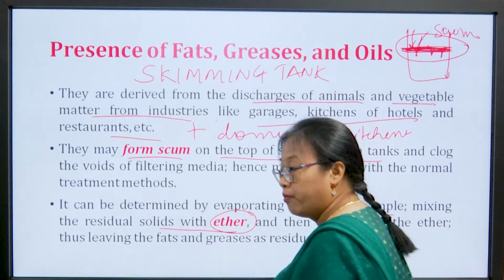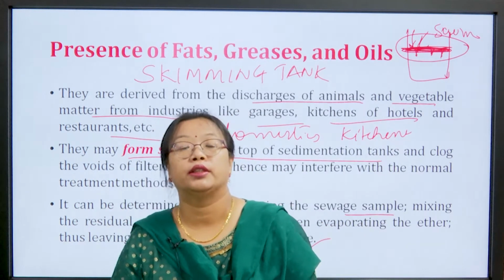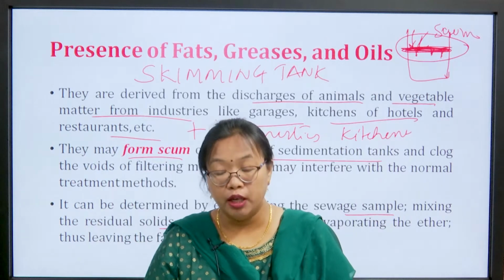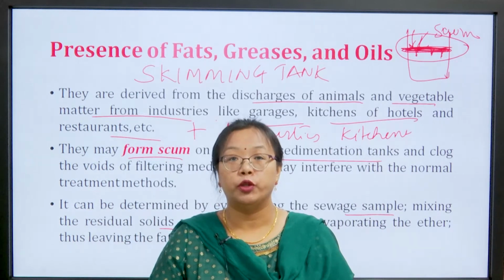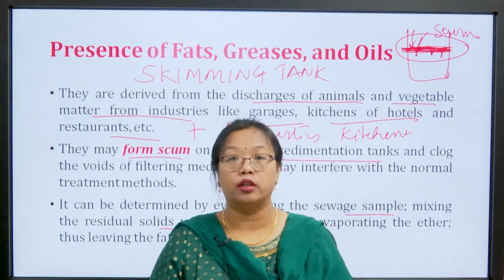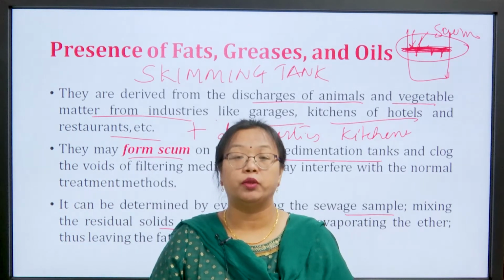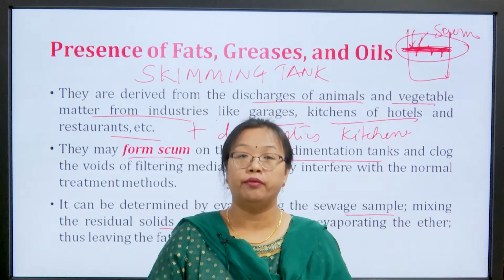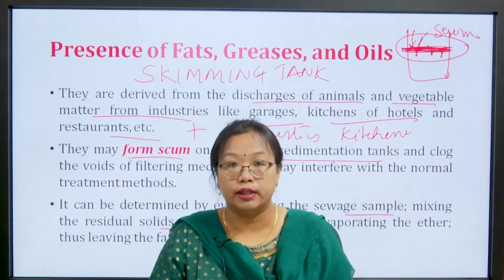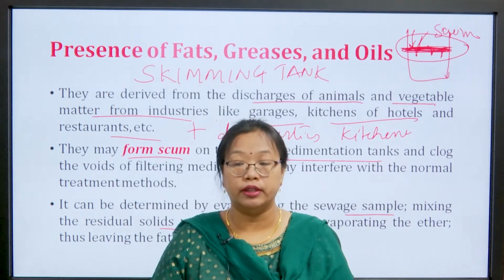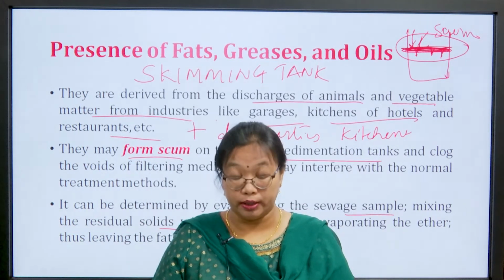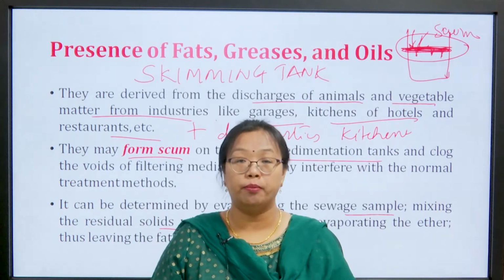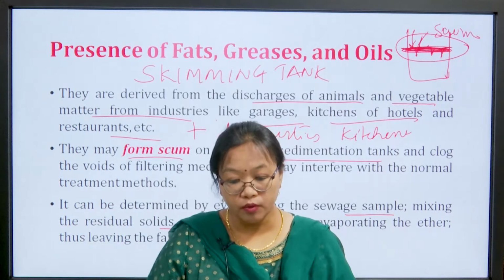So, fat, grease and oil are actually a very important part of the wastewater treatment system, because even if you have planned your wastewater treatment plant, your sewage treatment plant, very nicely, if in certain areas people have this habit of using more oil, more grease, in those places skimming tanks are actually very important. They have to be included.